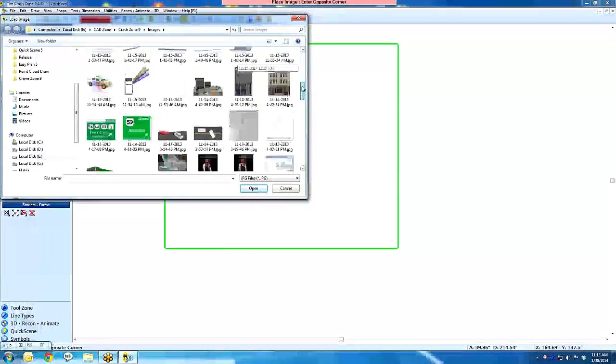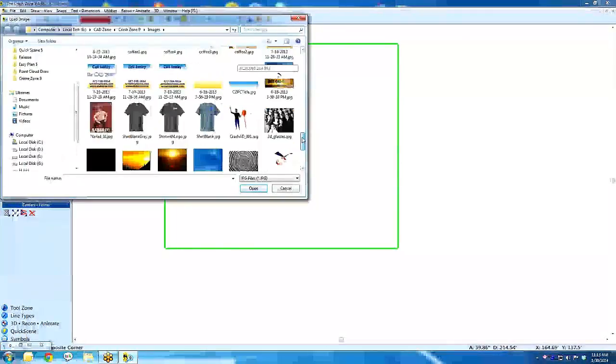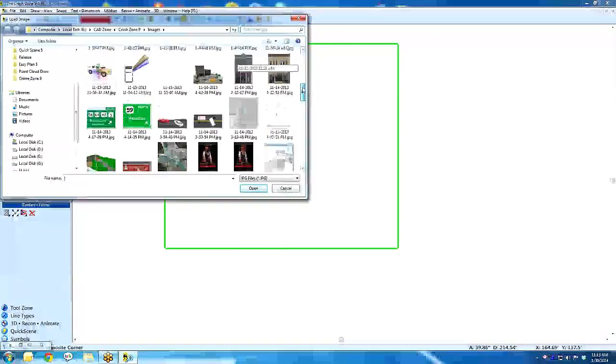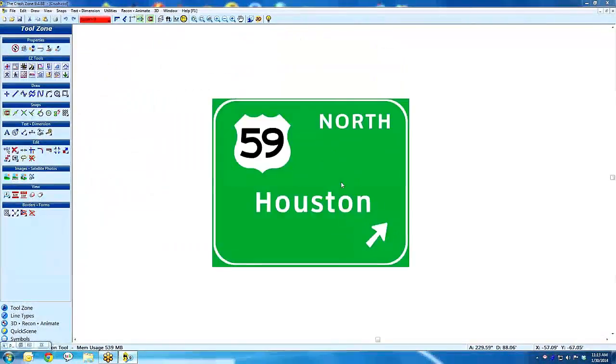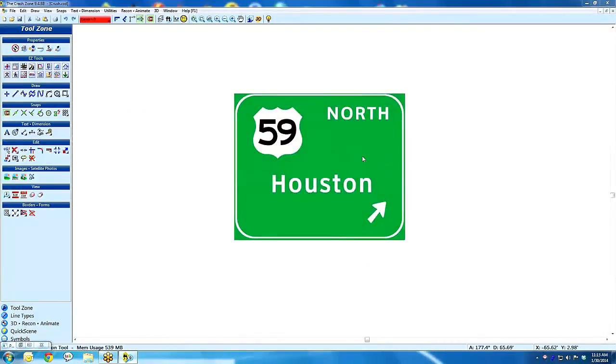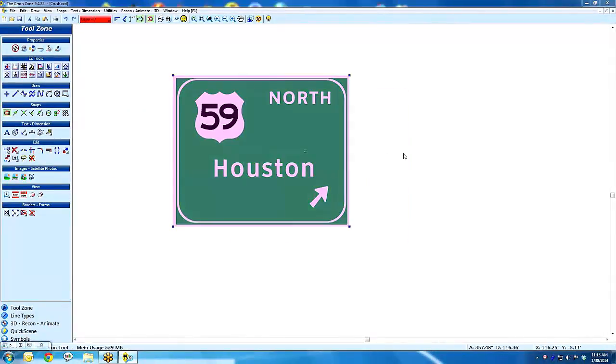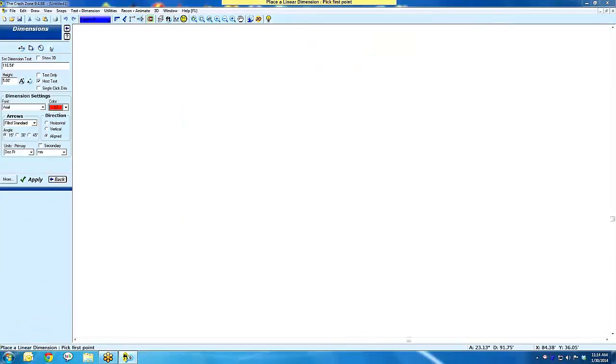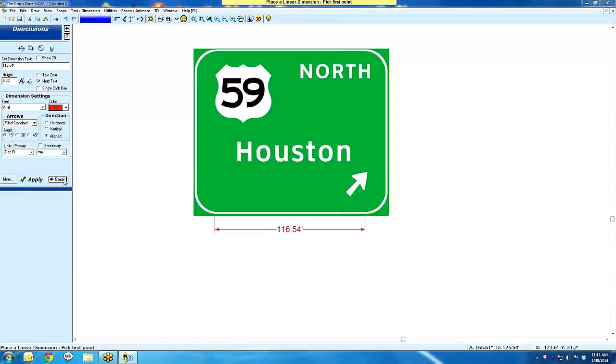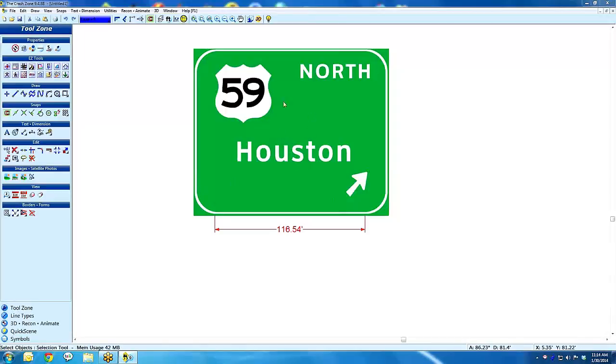I just don't happen to have a blueprint, but I have some images. You'll get the idea. Here, I'll bring in this. Let's say that's our blueprint. This is just a photo, like a nice graphic, but there's nothing I can do with it but scale it. So if I knew this was a wall here, that from this endpoint to that endpoint was 20 feet. So I brought this in, it's 116, I eyeballed it when I brought it in, it's not to scale. Pretend this is your blueprint. I know that this wall here is not 116 feet, but more like 50 feet, okay?